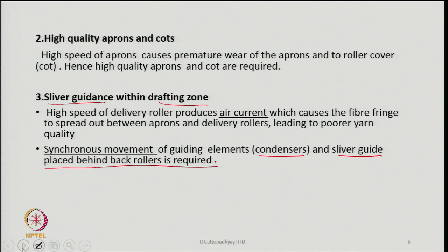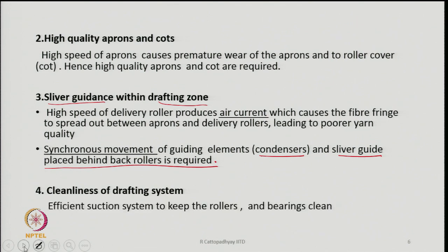That is what will be required. The other thing is the cleanliness of the drafting system. An efficient suction system is needed to keep the rollers and the bearings clean.